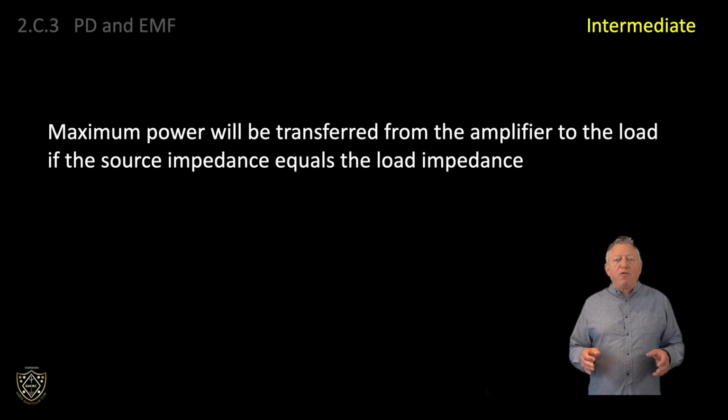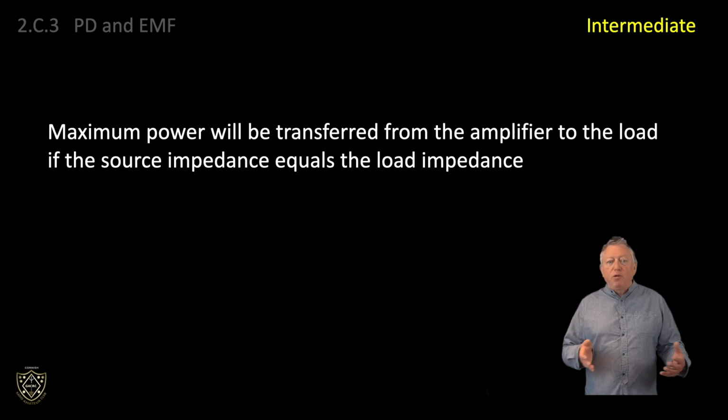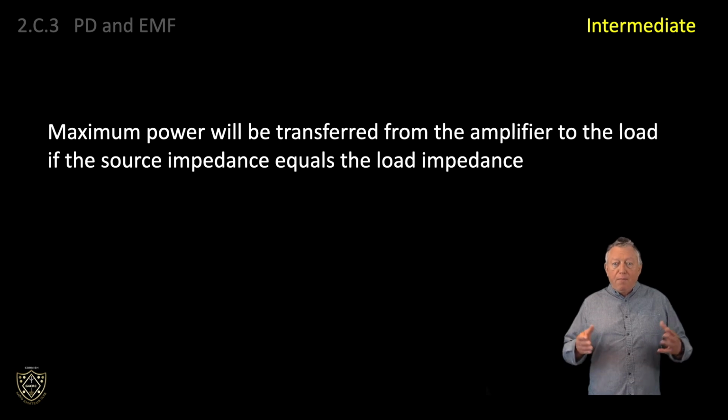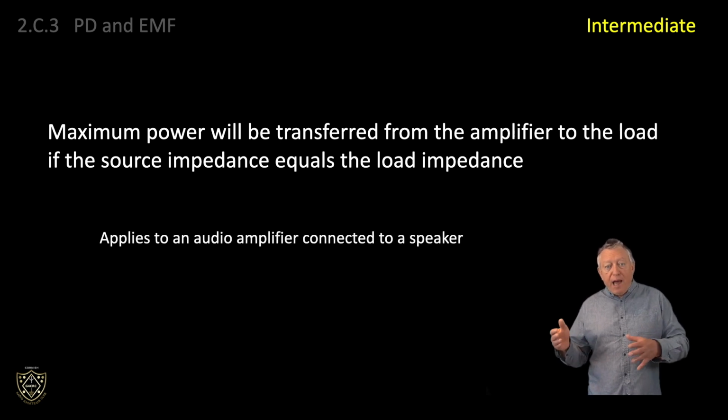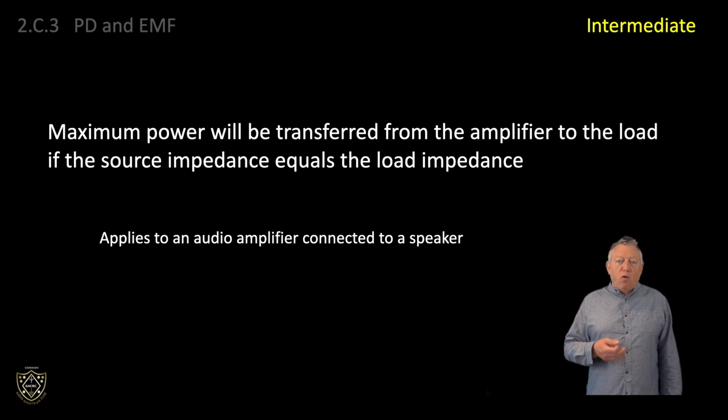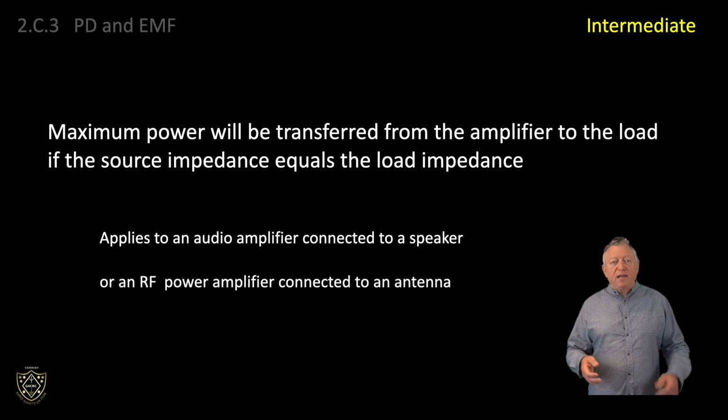The maximum power transfer theorem has implications for connecting an amplifier to a load. Maximum power will be transferred from the amplifier to the load if the amplifier source impedance equals the load impedance. This applies to an audio amplifier connected to a speaker or an RF amplifier connected to an antenna.